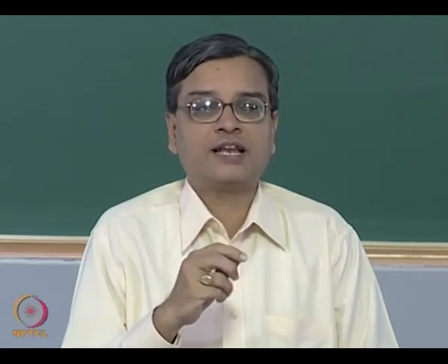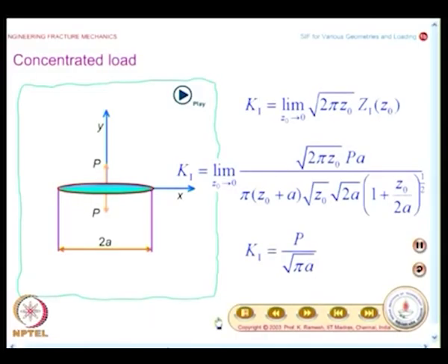And what we had seen in the last class, you had looked at the problem of a load at the crack surface. You have a concentrated load which is trying to open the crack faces, and for this case fortunately there was a stress function available, and once you have the stress function it is possible for you to find out the stress intensity factor by using this expression.